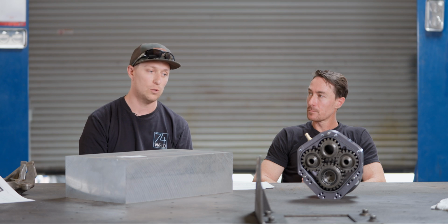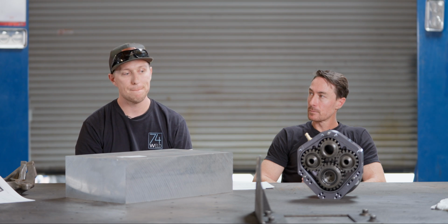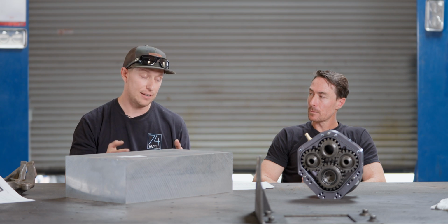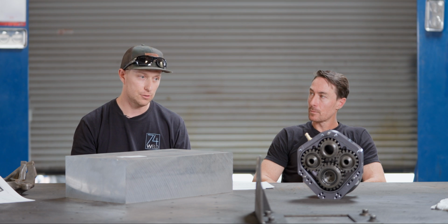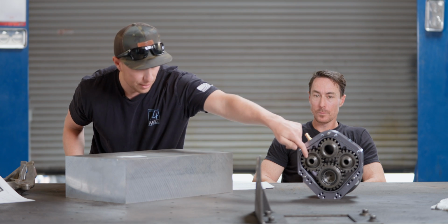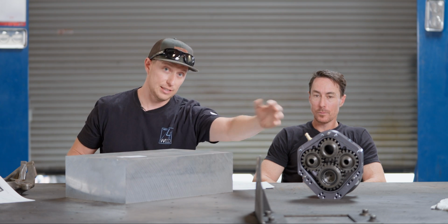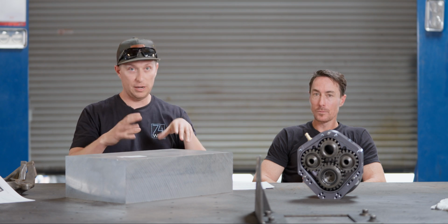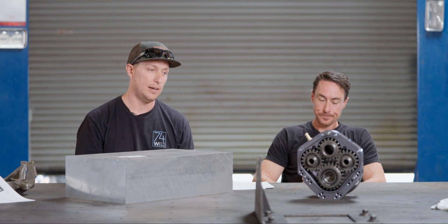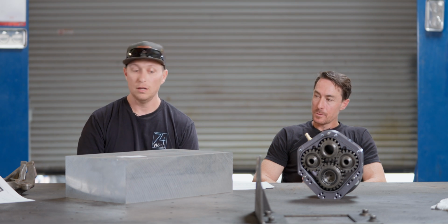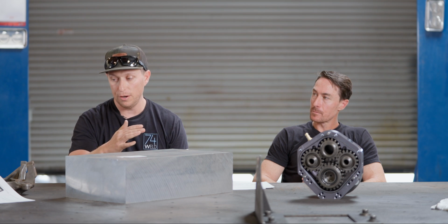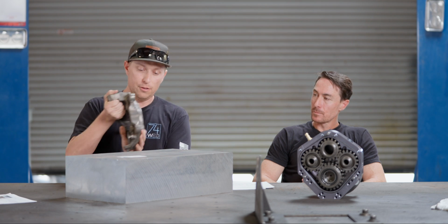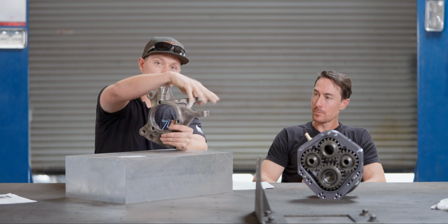So everything is really compact. You're doing what you would call a bearing stress on a material. When you load up this bearing, you're just compressing the material, the bearing's pushing into the bore and compressing the material. Whereas when we're looking at something with 7075, an upright or a knuckle, you have other members on it like steering arms.